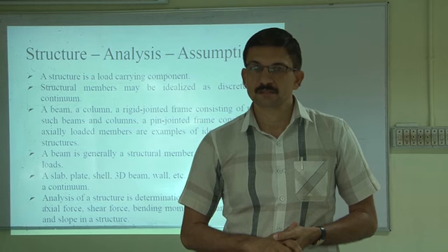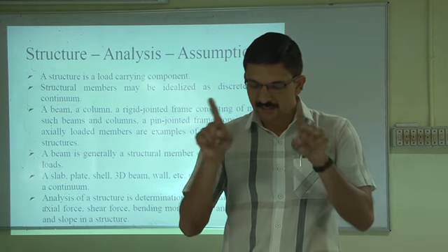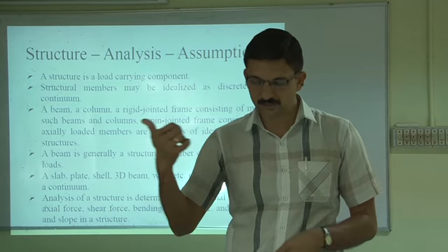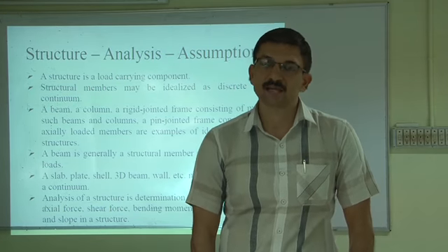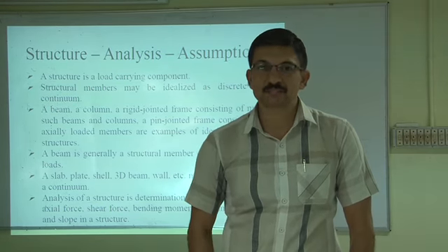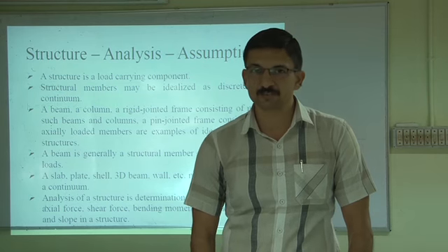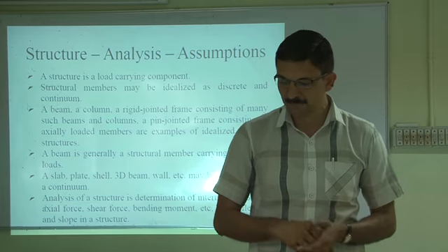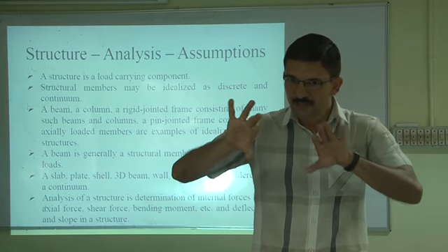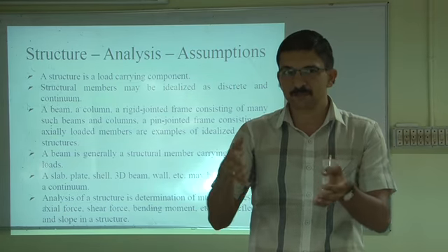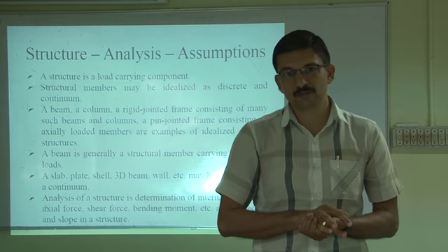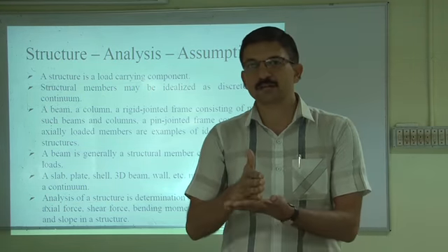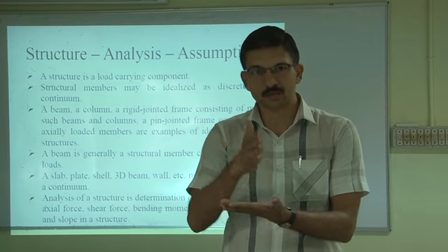So to decide upon the size of a structure, the shape of a structure, and the material to be made use of for construction, we are required to analyze the structure for, as it is given here, axial forces. Axial forces are forces acting along the longitudinal centroidal axis of the structure. Bending moments are moments which are trying to bend a structure with respect to the axis perpendicular to the longitudinal axis. Shear forces are forces trying to shear or break a structure along a cross section or otherwise.